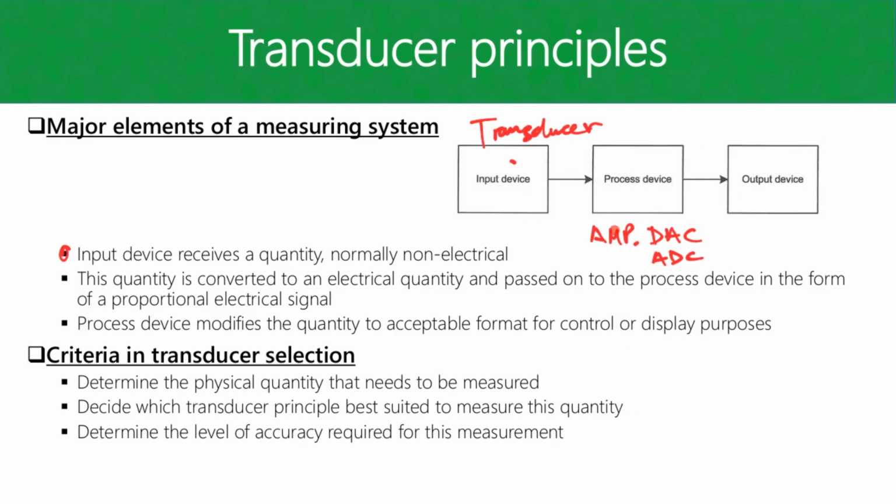And you guys will see a lot of the times you will have to implement an amplifier, especially amplifiers and filters, to get rid of noise firstly, and then secondly, to amplify your input signal as well, because a lot of the times the signal from your sensor is actually quite small.